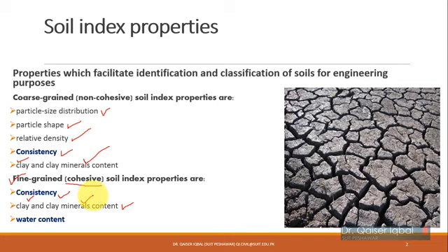Specifically speaking about montmorillonite, they are called expansive clays. They have potential to expand and contract, like here in this picture you can see. Upon drying, this soil has developed a lot of cracks. This is typically a property of montmorillonite, that it can change its volume a lot upon wetting and drying, which is usually problematic for your buildings, infrastructure, etc.